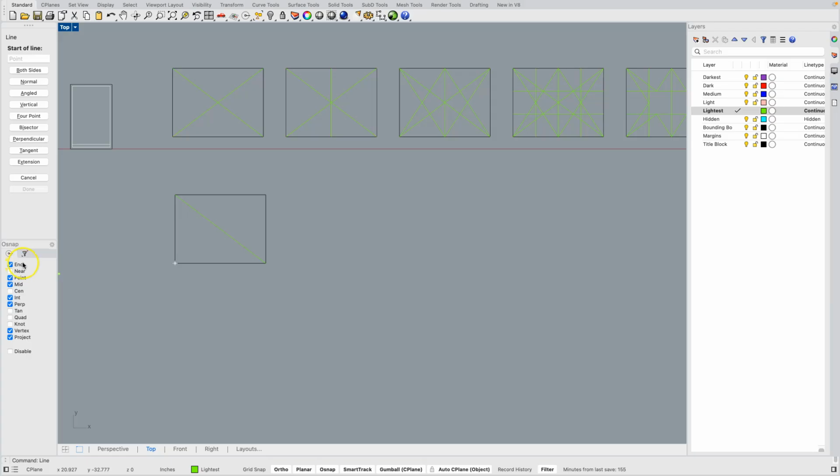And now if I look over here, you've noticed I've been snapping based on the snaps that were recommended to set up. I have object snaps of endpoint, midpoint, intersection, perpendicular. Vertex isn't as important right now, but project means I'm drafting on the ground. And so I can now enter this line. I've now made an X. Unlike hand drafting, I can now copy instantly.